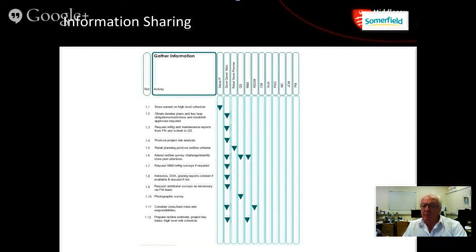Can I add something here as well, Steve? Yeah. I'd like to stress the word Steve said, that you would be sharing part of your development, not all of it, because you have to remember that in the IFC you do lose something. You lose the parametric relationships between the objects, inside the objects. We will be talking about this later. So you cannot actually do proper editing using IFC. You can only take from it to a certain limit and a certain extent. It is not like a native file. I just wanted to add that.